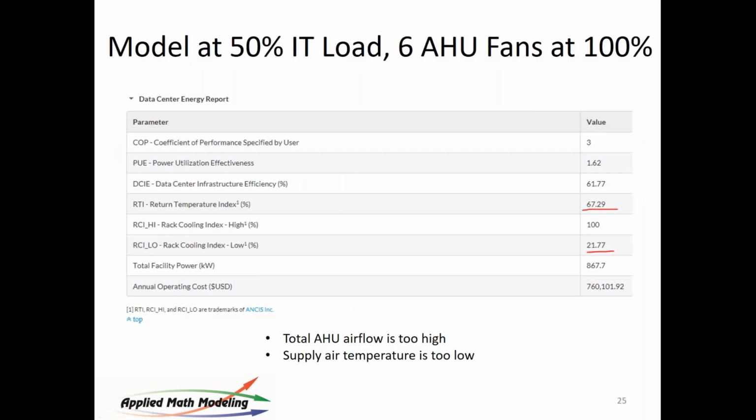So at 50% load with 6 air handlers running, because that's logical that you'd have only 6. If you do the math, that's all you need. In fact, it's a little more than what you need. You run them at 100%, again, it doesn't look that good. Your RTI is 67. You're too cold. Again, I'm assuming a 20-degree temperature here.